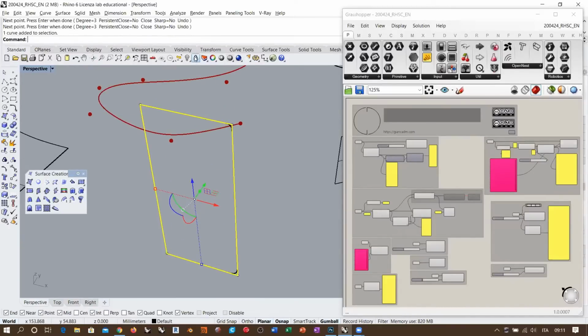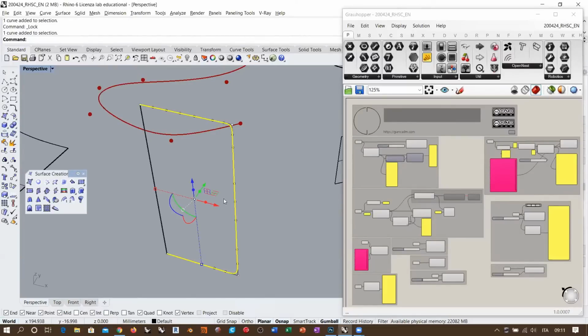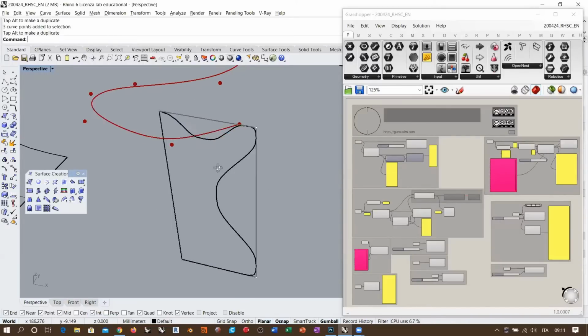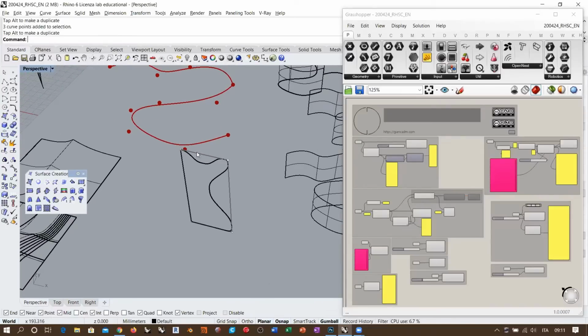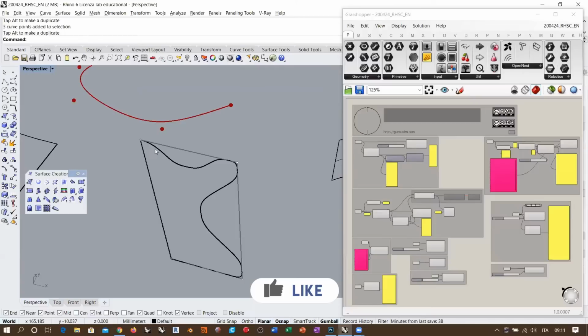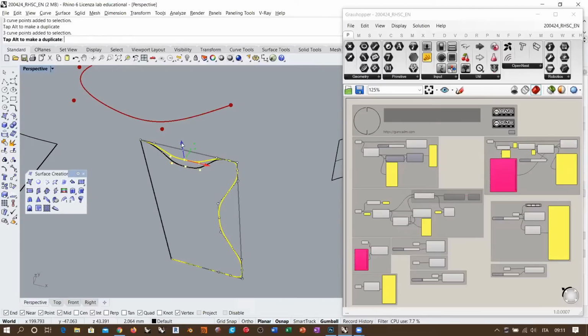I'm going to lock this rectangle so that we can easily select our curve. And I created this kind of 3 points structure because if I move them, I know that I can reach this depth inside the NURBS curve, and also this set of 3 points here in order to do something like this. Not because this is a particular design, but just to remind us of the power that we can access in order to create the right NURBS topology and being able to create some controlled deformation.